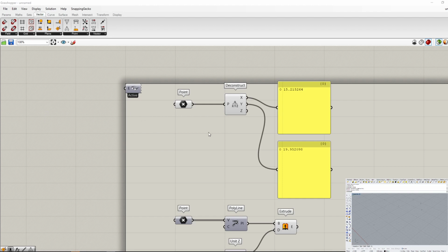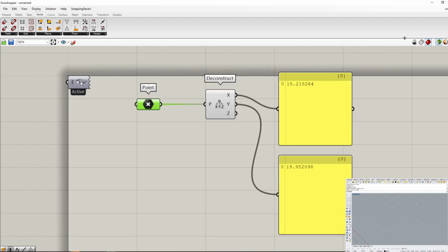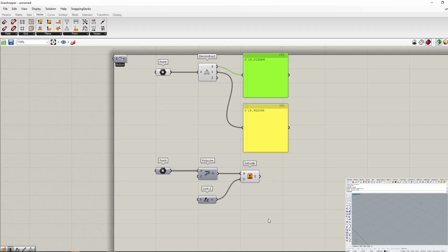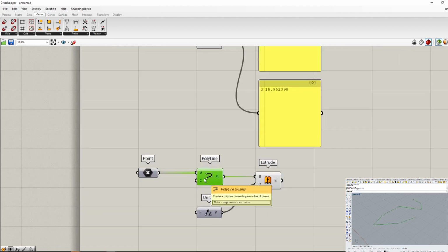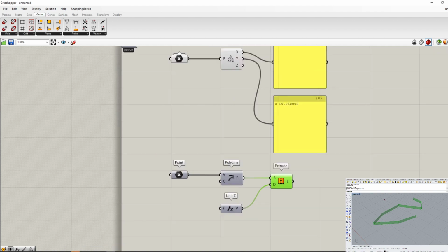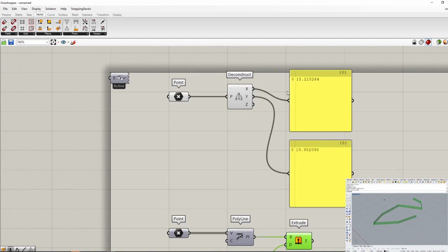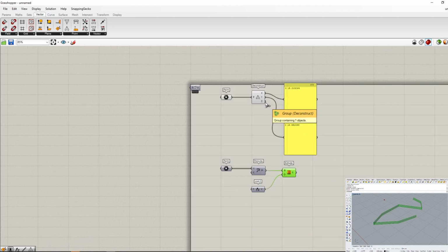We've also looked at how we can get that information and query things about it using a deconstruct component and then some panels to print to screen. We've also looked at how we can create geometry from geometry and geometry from that geometry. We've also looked at how to connect and disconnect wires. We've also looked at preview, baking, and enabled functions.